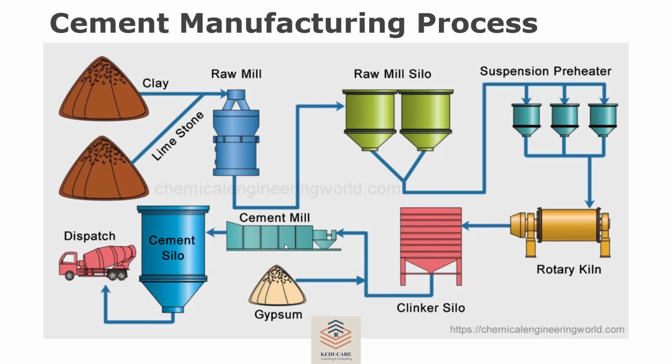The mixture fed to the grinding contains tricalcium aluminates, which are soluble in water. Gypsum reacts with them to produce tricalcium sulfoaluminates, which are insoluble in water. They retard the rate of setting. The gypsum retards the rate of setting of cement, thus giving time for concrete placing.